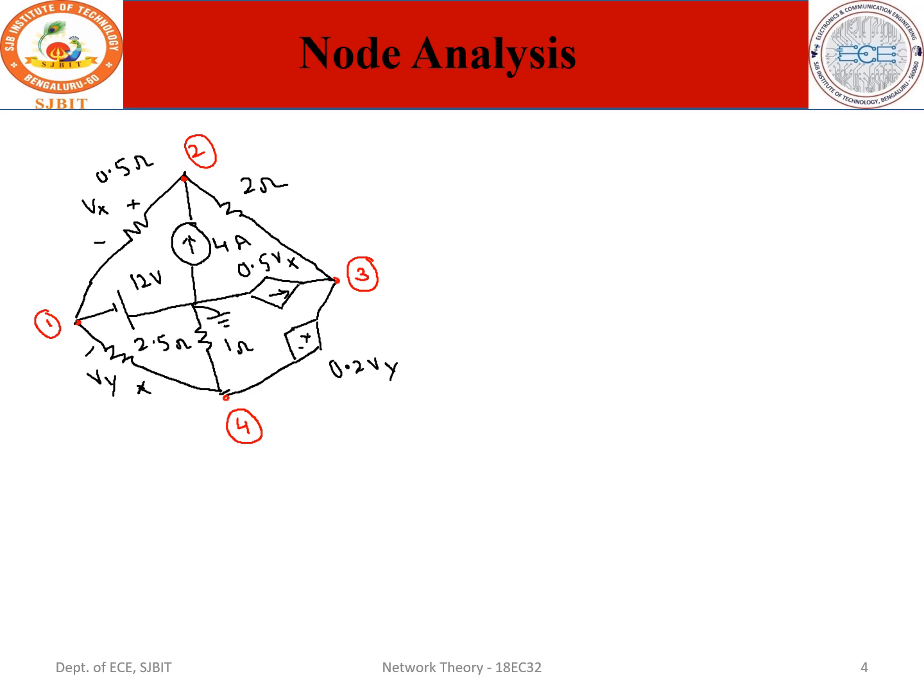Looking from the diagram, what are the voltages? The voltage is between the node and the ground point. Therefore, V1 is equal to minus 12 volt. The minus 12 becomes positive, connected to ground. Therefore, V1 is equal to minus 12 volt. Now apply the KCL at node 2. Apply KCL at node V2.